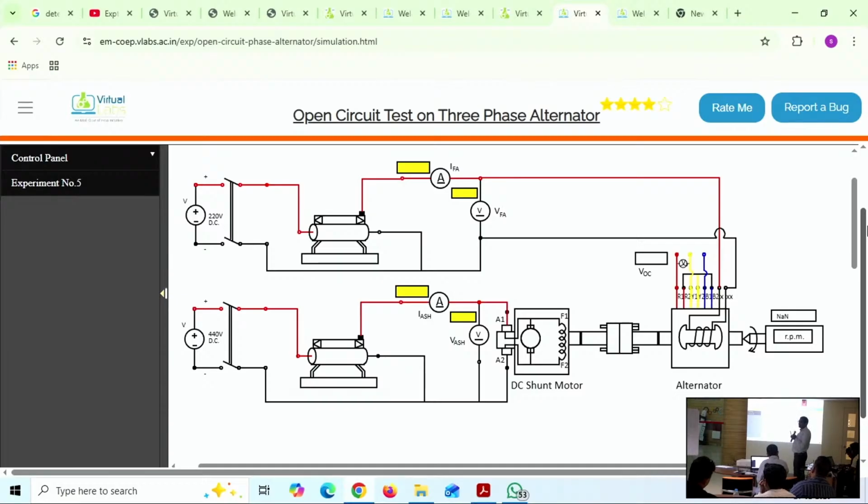In a three-phase alternator, the voltage is directly proportional to the excitation only. Because in a shunt generator, the field winding and armature winding are connected in parallel. Whatever armature voltage is developed is directly applied to the field. So that field causes additional current, additional flux, additional EMF. Again additional EMF, additional current, additional field. Again additional EMF. This process keeps on continuing within a very short span of time, and the DC shunt generator will develop its voltage, reaching its rated value.